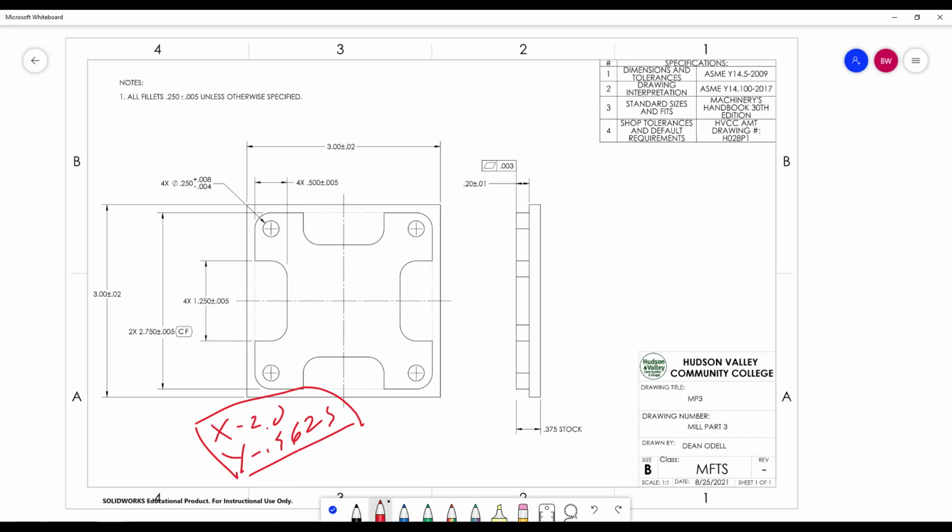Now, the next line, we want to come in here and we want to cut with the radius of the cutter with a max AE, or radial depth of cut, of 0.1875 max. Okay, could we get away with more? Oh yeah, but let's just work with it this way.